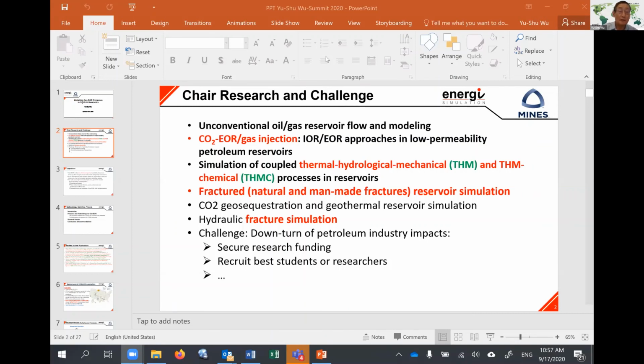The key here, we call nanopore confinement. Basically, once you have 2-phase or 3-phase, capillary pressure is very, very strong. Then in the phase behavior calculation, for the free energy calculation for each phase, you have to use the phase pressure, not just the oil pressure like a conventional compositional model, which uses one pressure. Here for the oil phase you use oil pressure, gas uses gas pressure, water uses water pressure. This differs by capillary pressure.